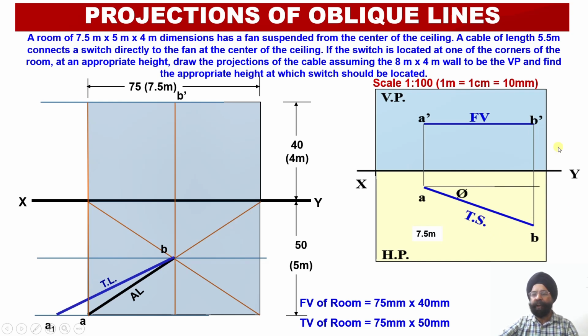So usually what we do, we have already got in most of the cases this projection line and we obtain this particular true length, but in this case it is the vice versa. Here we have been provided with the true length of the line in the top view. Now the reverse procedure has to be used over here.